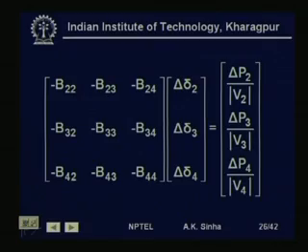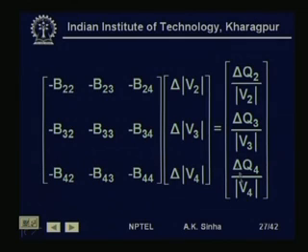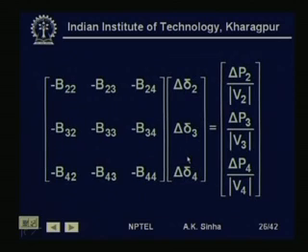So, they do not change with the iterations. Now, if they do not change with the iterations, it means we do not need to compute these elements each time. That is one advantage. The other advantage is that once we have triangularized these matrices, we can keep the matrix elements stored because they are not going to change, and what we need to do is only a forward operation on this vector and then, using a back substitution, we can calculate the value of the unknowns delta v and delta delta.